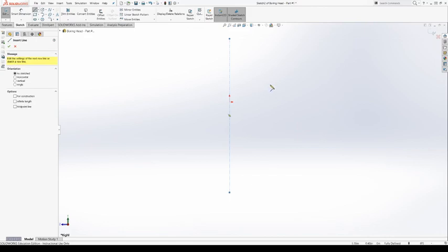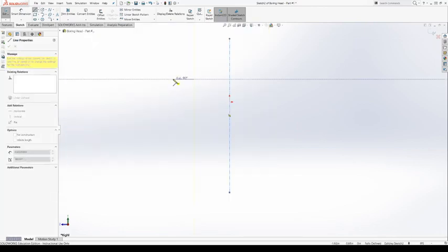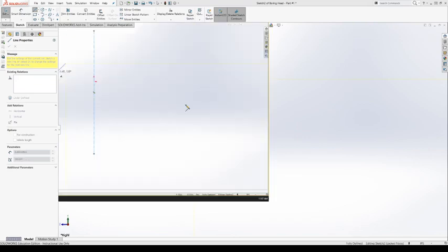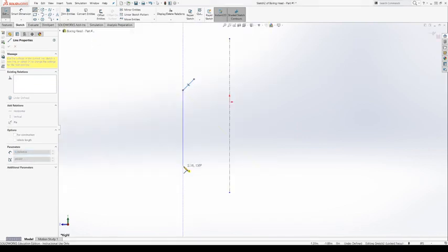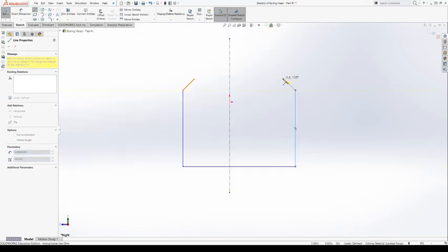and now I still have my sketch open, and I'm just going to draw the general shape of my part, right? I have my blueprint open on another page, so I'm going to look at that. I'm just going to start off with this edge, right? Comes down, has a chamfer. We're going to go across. Going to go up. Chamfer is going to be equal.